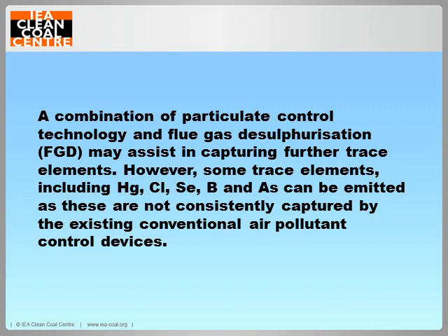The arsenic concentration in the bottom ash, fly ash, and the FGD residues was about 5 and 30 milligrams per kilogram, respectively. International analysis of fly ash from coal combustion shows that arsenic is enriched, as with other trace elements, in the finest fractions which may not be captured by some particulate control devices.